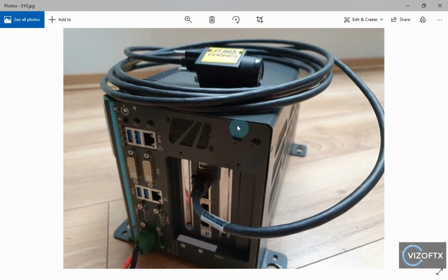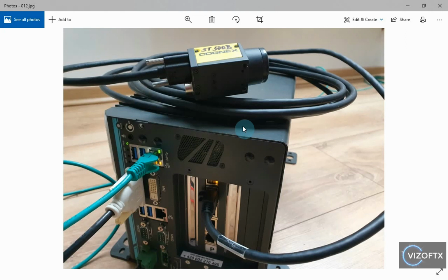This is how it may look when everything is connected to a computer with a display and with communication with other systems. Often, we need to connect more cameras than 4. The standard license from Cognex allows the use of 8 cameras. However, it is possible to purchase an extension for an unlimited number of cameras. But what if we need to plug in so many cameras? If the computer allows it, we try to connect a sufficient number of network cards.